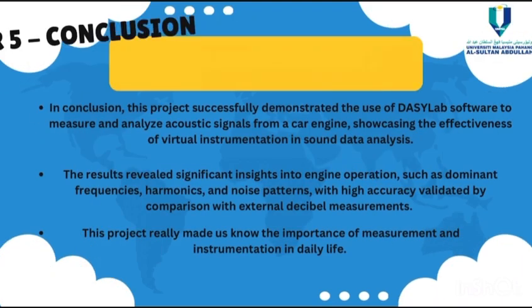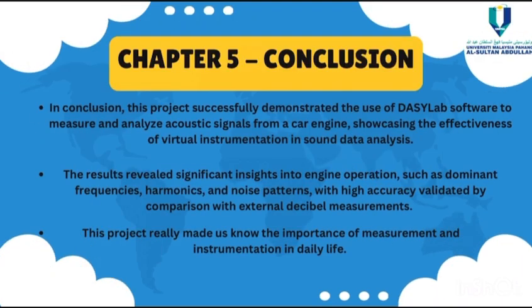Finally, let us conclude. In conclusion, this project successfully demonstrates the use of DaisyLab software to measure and analyze acoustic signals from the car engine, showcasing the effectiveness of virtual instrumentation in sound data analysis. By integrating a condenser microphone as a primary sensor, the system accurately captured and processed engine sound data in both time and frequency domains. The results reveal significant insight into engine operations such as dominant frequencies, harmonics, and noise patterns, with high accuracy validated by the comparison with the external decibel measurements.